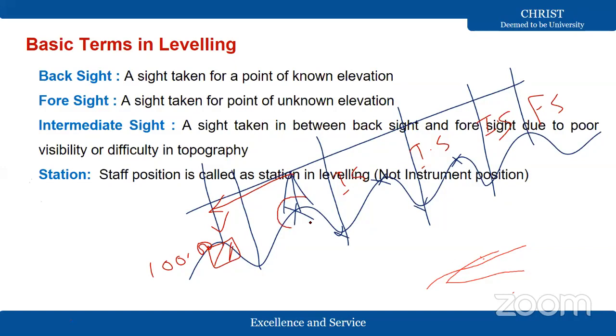That is called a staff position, it is called a station in leveling, not the instrument position. This is not the instrument station. Station means staff position. This one. These are the stations in leveling. Okay. These are the stations wherever you are keeping a leveling staff. That is called station in the leveling.